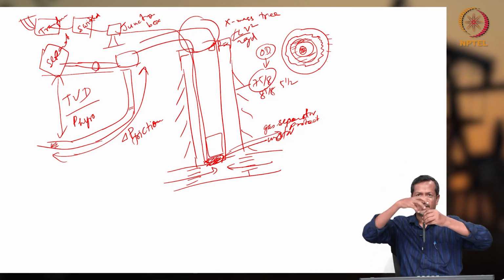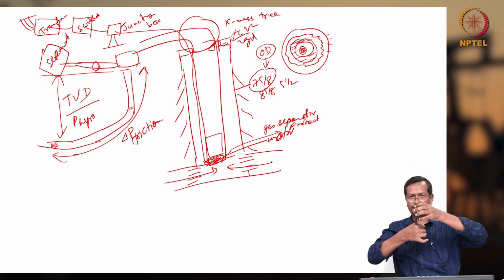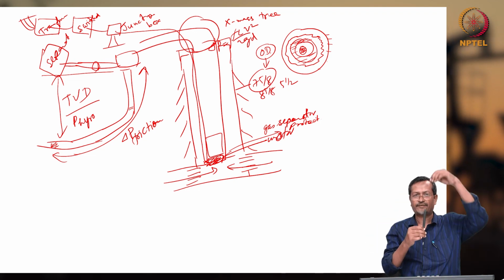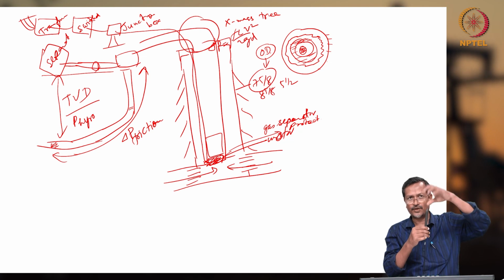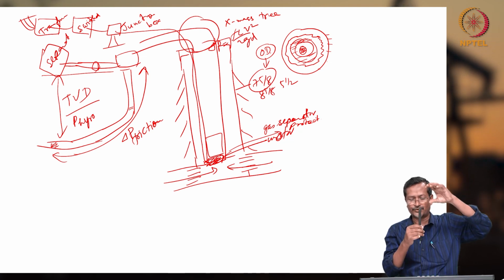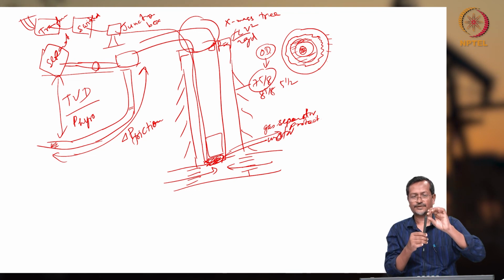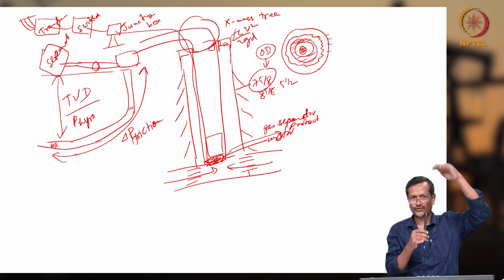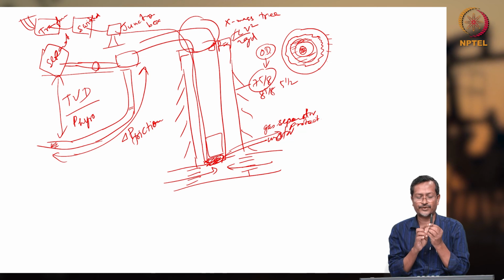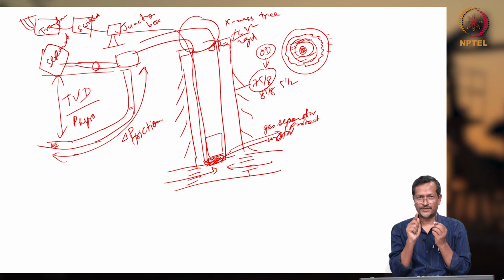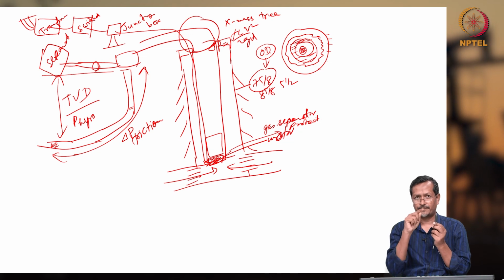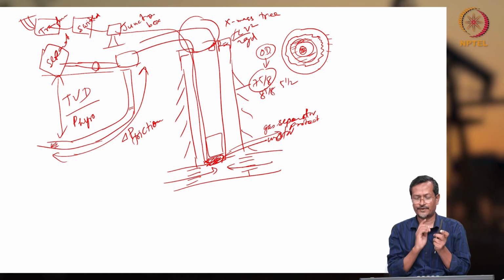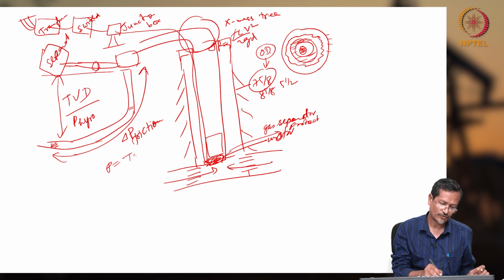Okay, and it will be connected in many places. It will have radial bearings in many places, so that when it is rotating it will not vibrate, and it will have some thrust bearings also, so that if axial load is coming, the axial load should not get transferred to the pump, the gas separator, the protector, or the motor. So there must be thrust bearings in many places, because this shaft is designed for torque only. Torque means power. How is it related? P equals T into omega, torque into rotational speed. So if your speed is changing, torque can change for the same power. Okay, so the formula is P equals T omega.